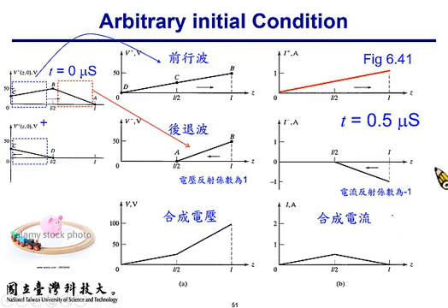On the other hand, the BC part continues its propagation to the right and forms the leading edge after 0.5 microsecond of propagation. And the CD part, which is originally the V minus component, with 0.5 microsecond time delay, reaches the left end and gets reflected and forms the second half of the V plus signal, as the CD component shown here.